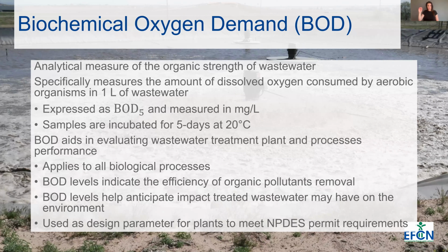BOD is important for our biological process because it aids in evaluating whether the wastewater treatment plant and processes are performing as they should. You can apply BOD calculations to all the biological processes to understand how much BOD is coming in and how much BOD is being removed by the process. The BOD levels indicate the efficiency of organic pollutant removal, and help to anticipate the impact the treated wastewater could have on the environment.